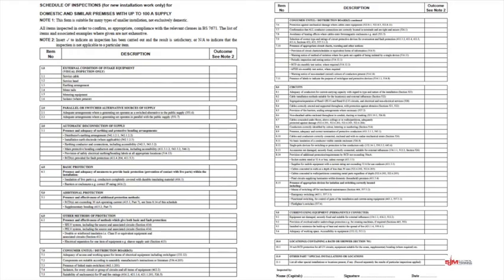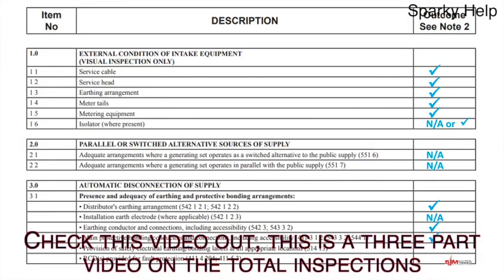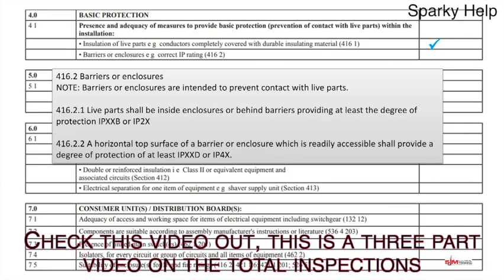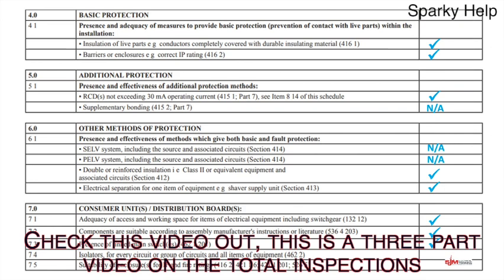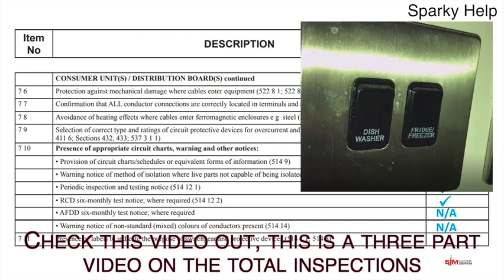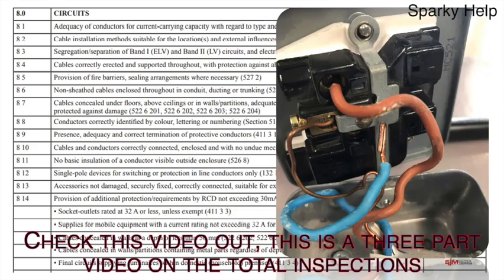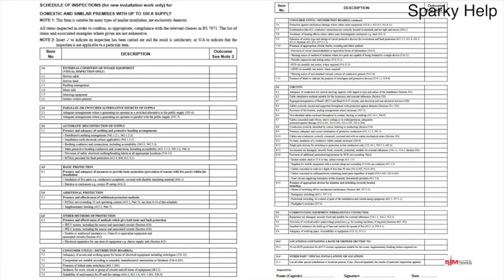Well, in the previous one we had two sheets consisting of all these different tick boxes, and we had the main headings, and then underneath each main heading you had the subdivision of what you would then check on each one. So for example, external condition of intake equipment, visual inspection only, it broke it down to service cable, service head, earthing arrangement, meter tails, metering equipment and isolator where present. I've just done a video on it, so go look at it because it's over 3 parts to cover all of this information for things that you would check.